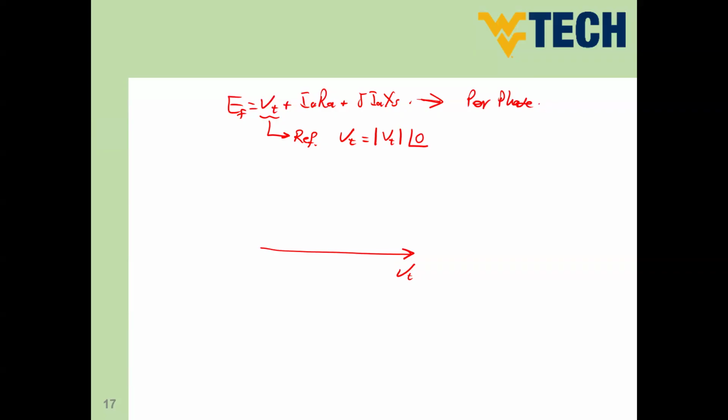Let's now state the lagging power factor case. I'm going to start with the lagging case. Lagging case means our load is going to be absorbing current lagging this volt. So I'm going to draw the current vector on the diagram here. It's not going to be added to the diagram, because by the end, the phasor diagram is going to be the summation of voltages only.